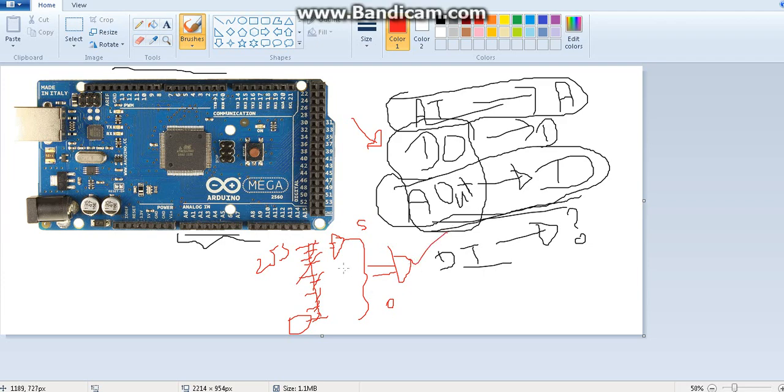Okay, guys, what I have said now is very, very important. This is the scenario actually happening. If you are saying the half value, let's say 127 for the moment, that is actually almost half, then Arduino will refer that you are telling the half. So Arduino will take the number of counts and refer it with this voltage range. So it will find it is almost 2.5 voltage. So Arduino will give 2.5 voltage output in the particular pin.